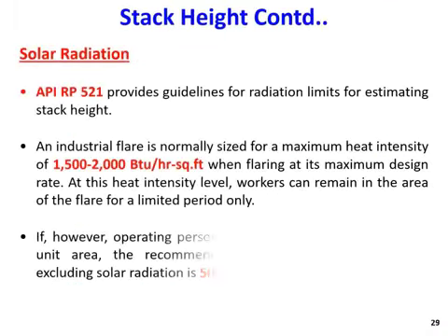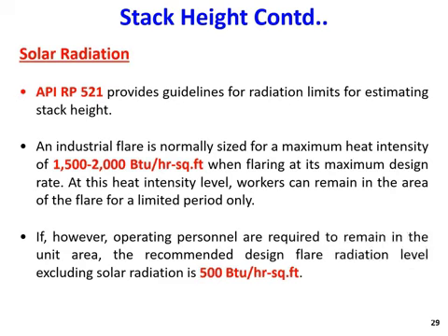Okay, some additional points about the flare height. The radiation is one of the most important factors that determine the height of the flare. To calculate that height, we use a standard, API RP 521.